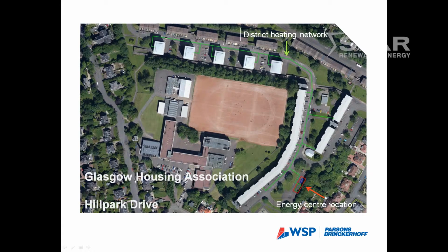Biomass is quite tricky on the site because of access constraints and the need for a flue. The site is on top of a hill, nowhere near any watercourses, and there wasn't enough space for a borehole array for a ground source heat pump. So that's why we worked with Star Renewables to progress to a second detailed feasibility study and develop the air source heat pump concept for district heating alongside the actual design for the district heating system itself.